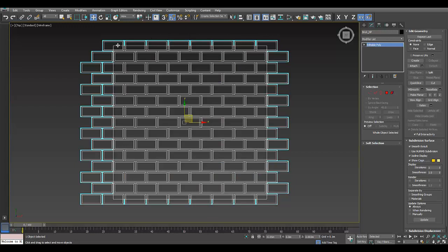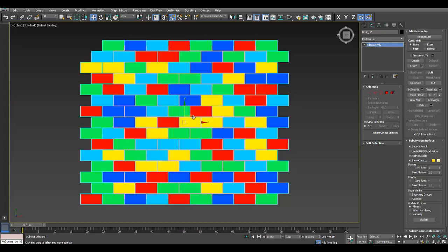And what you'll notice is the bricks are offset from the edge as well, because you don't want anything lining up perfectly with the square or the edge of the low poly. Otherwise you're going to start getting really noticeable patterns, especially when it tiles over large areas. So what I've done there, as you can see, is put all the colour IDs in order, so it's all random in the middle, but around the edges it all matches up.